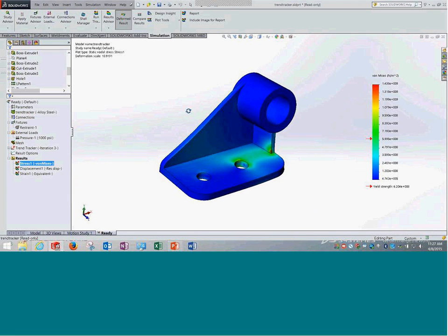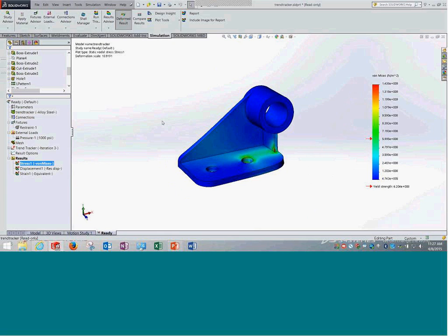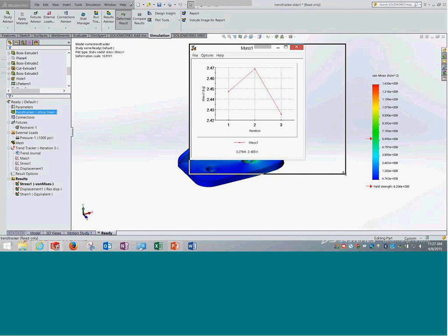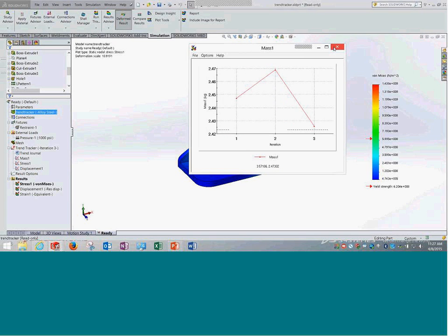It is a question. So Trend Tracker is a tool which sits in the background over here silently and is going to tell us how the trend is happening with these changes. Have I actually improved the model or have I spoiled it? So here it has stored the mass variations for those 3 iterations. You can see, obviously when I increase the dimension, the mass has gone up.